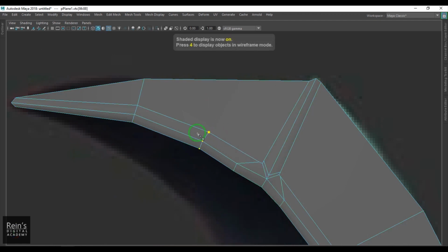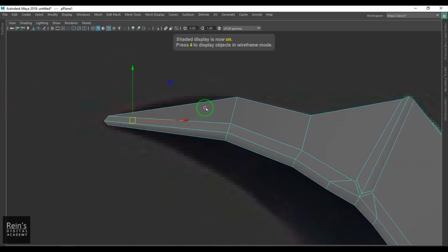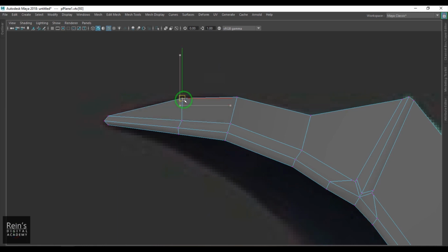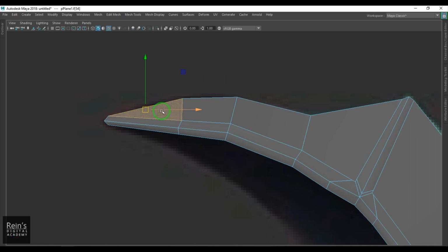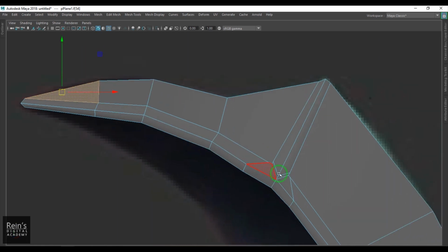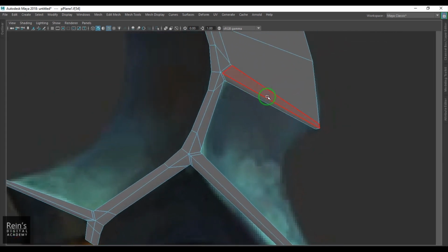Okay, so I need a line here, hold control, drag, and then again use the multi-cut tool. Okay, again multi-cut tool. So if you could see, this is a triangle until I've added this line. So I just add that vertex. This is a triangle now. If you could see, I can fix that. I'll fix it once I complete the total model. Don't worry about that.